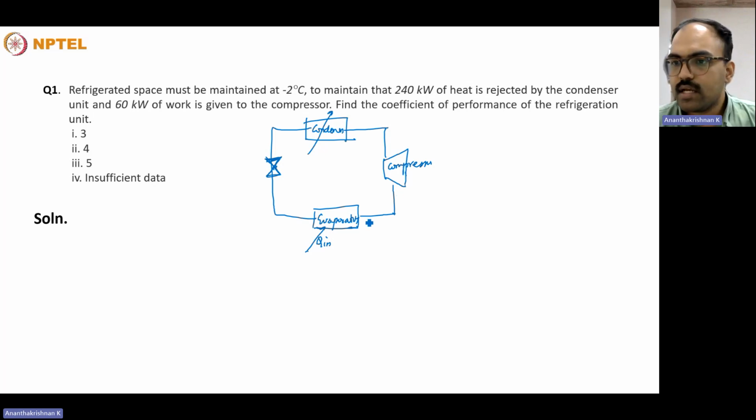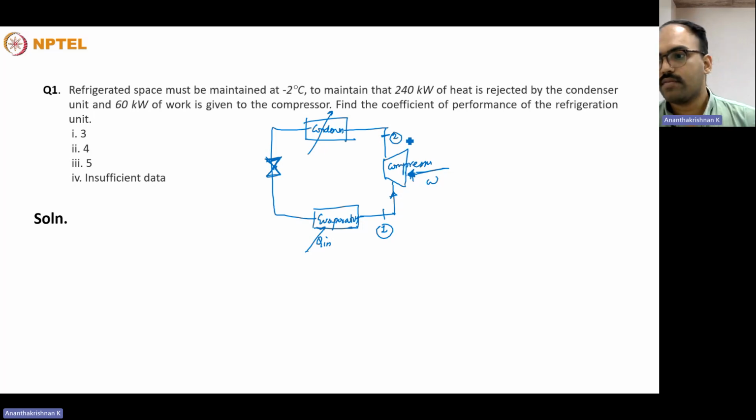So in this process, the refrigerant becomes vaporized in the evaporator. You can state it as point 1, and from there, external work needs to be done in the compressor to raise its temperature and pressure, and most probably the vapor will be in a superheated condition, much above the freezing temperatures.